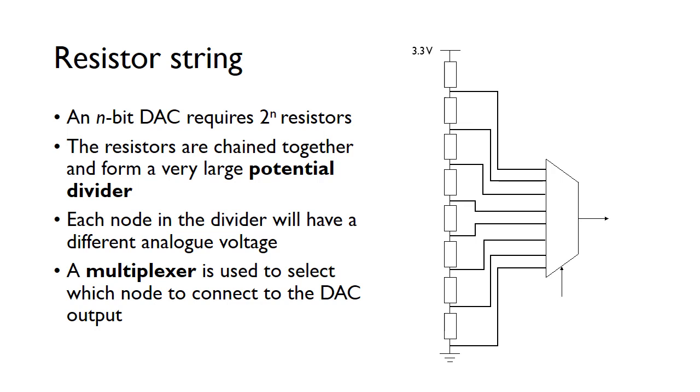And then these will go into kind of like a multiplexer. This will be the kind of control bus. So by specifying which node to output onto the output, we control what the output voltage is. So for example, I think there's 8 here. So if we say this is 0, so that's 111. It'll start from here, 0, 0, 0, 0, 0, 1, 0, 1, 0.